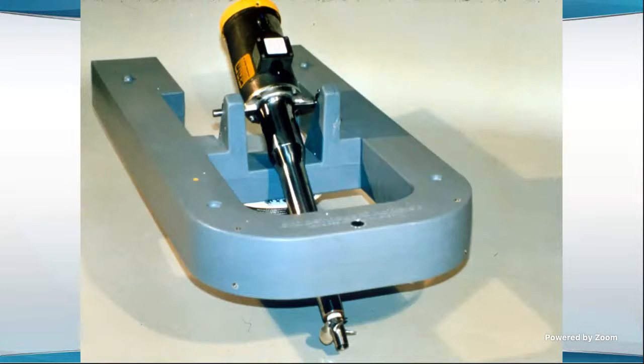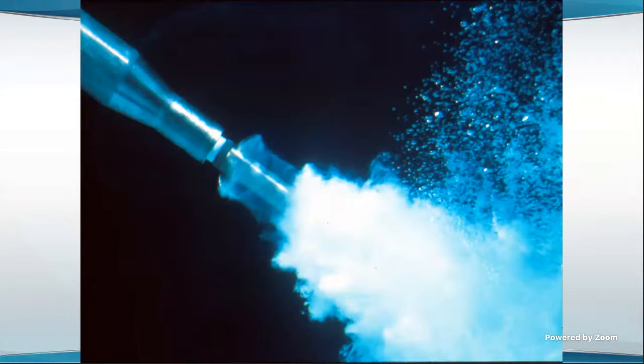It's a different mechanism. What it's got is a rotating hollow shaft inside of that thing, and there's a diffuser down near that impeller, and the impeller jets the water forward, and there's a housing around that hollow shaft. It's got a hole in it up here near the aerator, and air is forced down in there by the atmosphere as that impeller evacuates the shaft. So it's an aspirator type device, and you can see the water comes out with air in it and very small bubbles. It's a fairly efficient device.